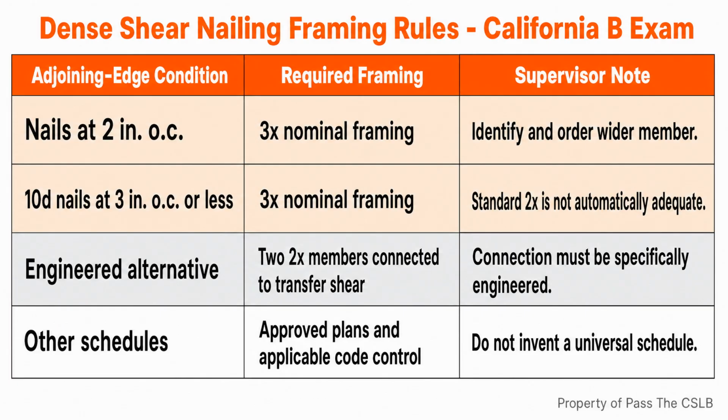A shiner misses the backing. An overdriven nail damages the face. One fails because there is no framing connection. The other is suspect because the panel material under the head has been crushed.